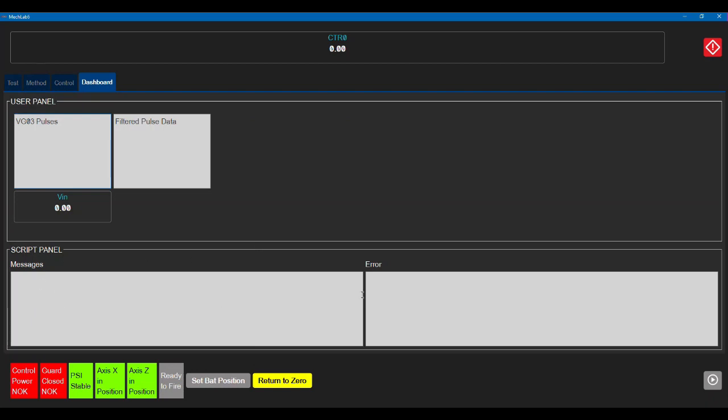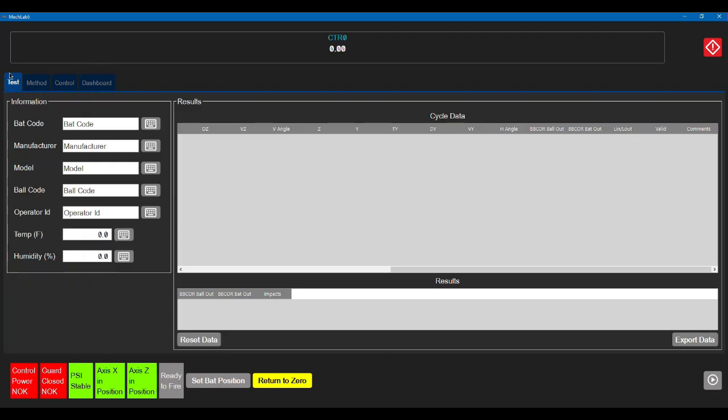The script panel is always available. If an error occurs in the script and calculation, either from a typo or from a bad value coming in that causes the Python script to error out, then that information, including line numbers where the error occurred in the description, are displayed in the error field here. But you can also put print statements into the Python script. Those are captured and relayed back here. So all sorts of information is available to the operator.